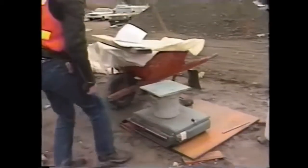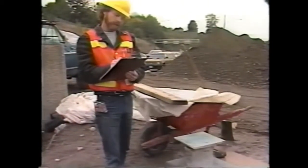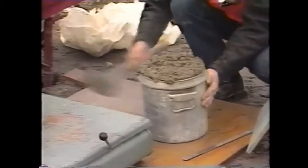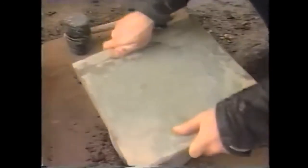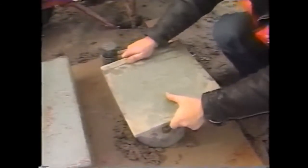The first thing to do is place the empty bowl and strike-off plate on the scale or balance and record the weight. The bowl is then filled in 3 equal layers of concrete, with each layer properly consolidated. Consolidation requirements are the same as for the air content test. If the slump is less than 1 inch, you vibrate. If it's more than 3 inches, you rod. And if it's in between, you have the option. The concrete surface is struck off and finished using the strike-off plate. The bowl must be exactly level full.